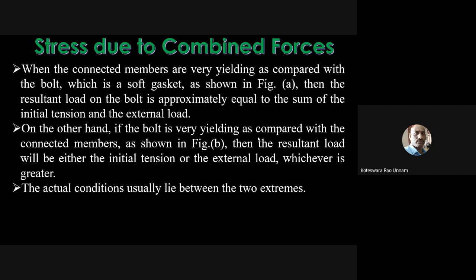That means you have a situation in between these two extreme conditions. If the actual situation is between these two extremes, then in one case the bolt is taking the total external load, and in the other case the bolt is not taking any external load at all. So these two are the extremes: zero load or maximum load. A practical or actual condition lies in between these two conditions.